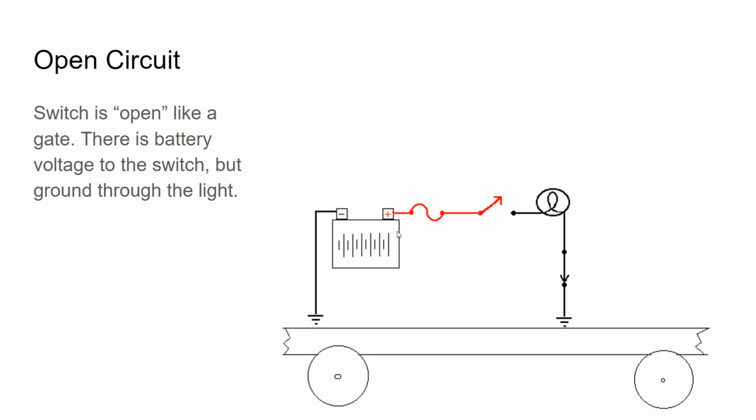A couple of things that we have on here, I'll cover them really quick. I talked about the battery already. This fun little squiggle here is a fuse. That's the symbol for a fuse. We've got a wire. These little dots here on the wire indicate typical connections on most wiring diagrams. Some wiring diagrams are a little different, but I'm going to keep this one simple. This little arrow that's running off into nowhere is a switch. You think of switches kind of like looking down on a gate from a bird's eye view. This one is open. This opened the circuit.